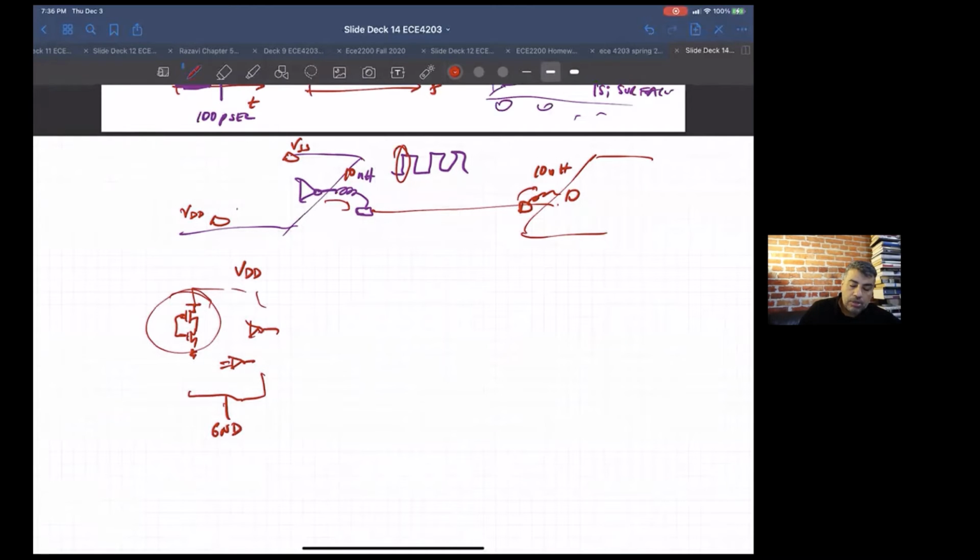The other equation to remember is the voltage across an inductor as a function of time is the inductance times the change in current as a function of time. So what happens, remember, especially your flip-flops, your clock is getting clocked all the time. So you're clocking hundreds of thousands of gates at the same time in your flip-flops. That means it's like having a current source hooked up to VDD that, every time there's a clock, you get a sharp spike.